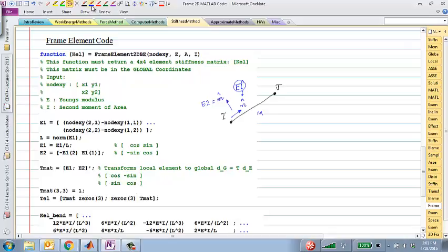And now we have added this element T3 cross 3. We had this cosine, minus sine, cosine matrix, which was a 2 cross 2. In MATLAB, if you say Tmat 3 cross 3, which doesn't even exist till now, is equal to 1, what MATLAB does is it extends the size of that matrix, and it creates a 1 here, and whatever elements are not specified, it creates zeros.